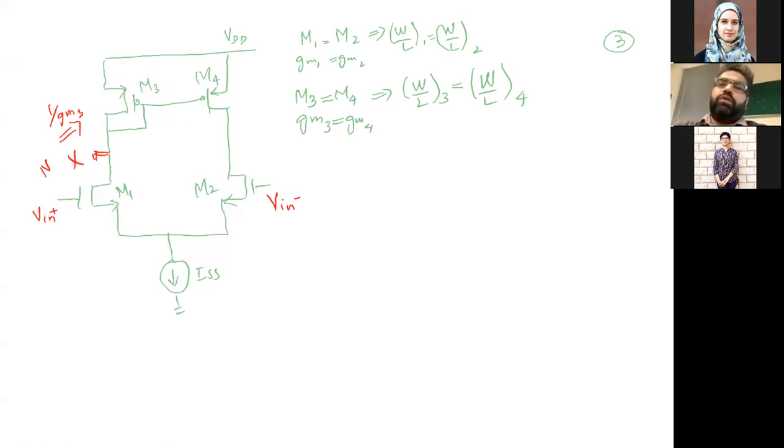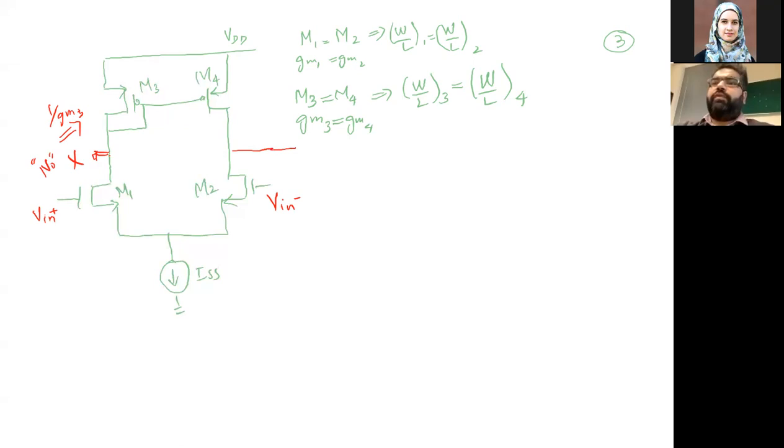No. So this is the point where I should take a single-ended output, which I'm calling V out. So I take the output V out and feed it to an amplifier. Okay, a single-ended amplifier we are feeding it, and we are still getting the benefit of the differential topology, right? So that's what we want to do. And now this V out is going to be with reference to ground.